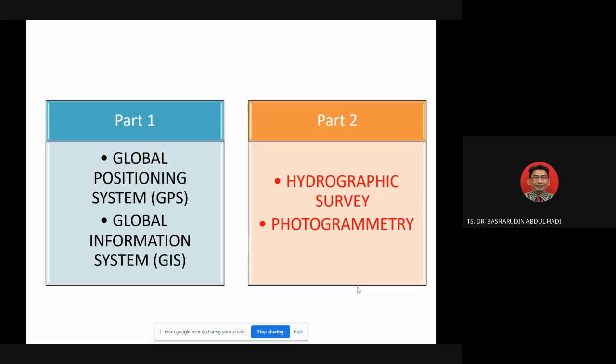So part two is we want to measure what we call seabeds, riverbeds, and lake beds. Because underwater you also have land, and you also have rock formations. How do you know that the reduced level of that rock is higher than point B? We use laser, radar waves, or a tape for shallow water. This is called a hydrographic survey, where we measure the underwater topography.